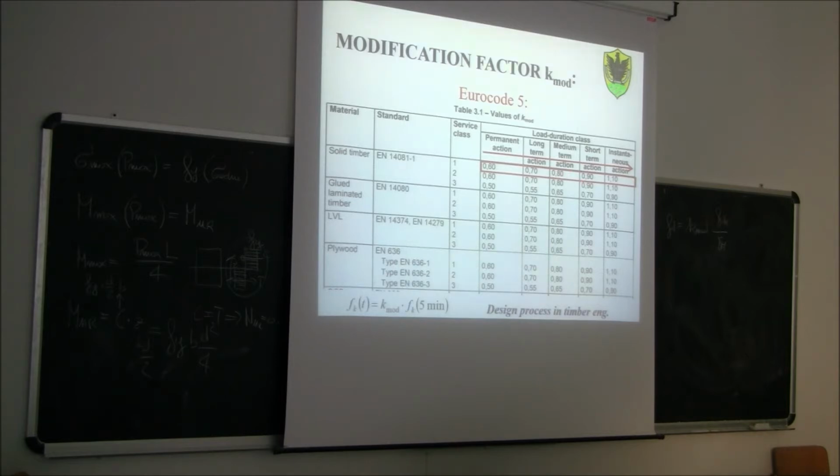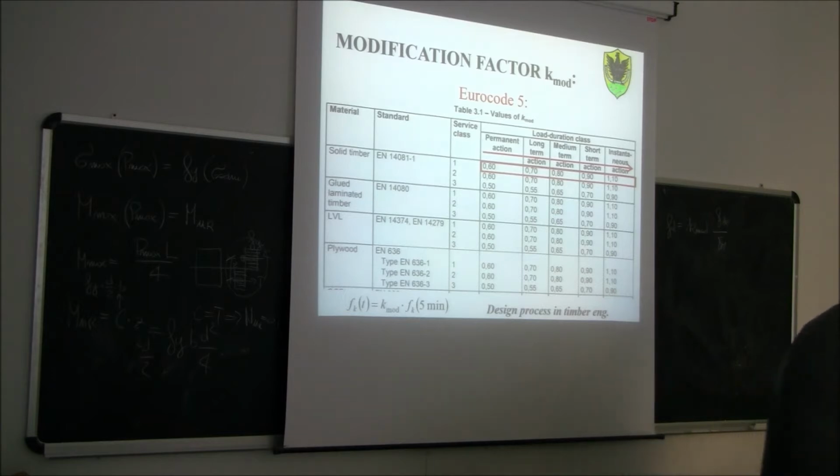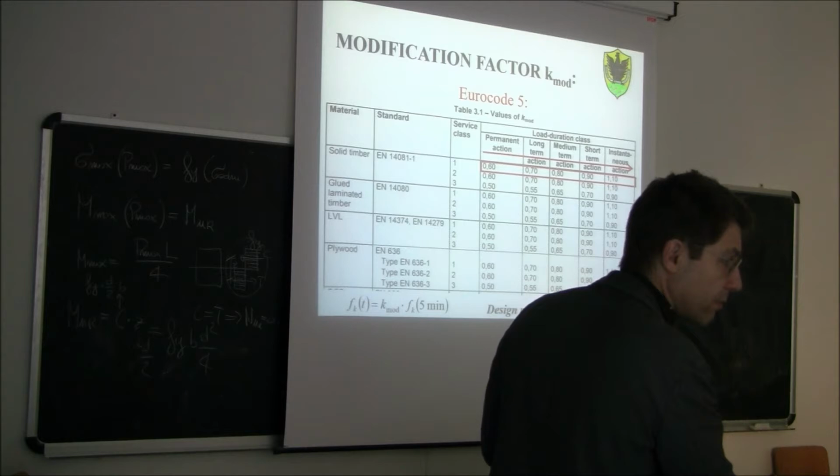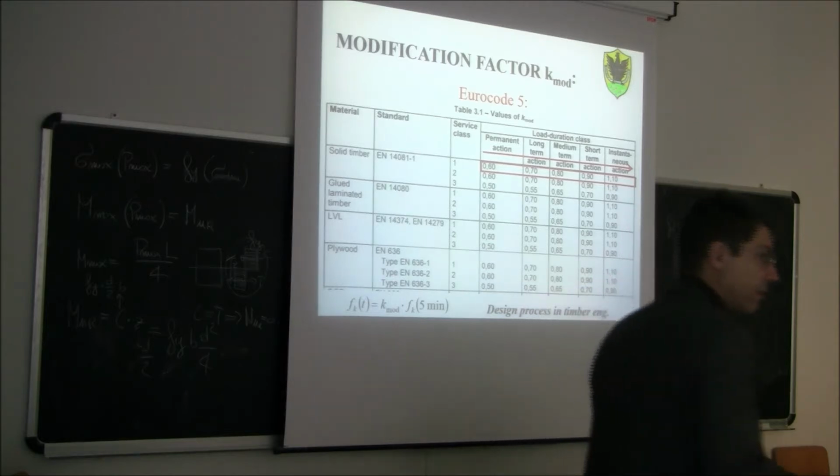Because shorter load duration corresponds to higher strength. Remember that when you design for earthquake, you have to increase the strength. You have to use a 1.1 coefficient.